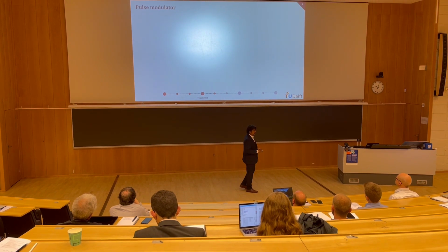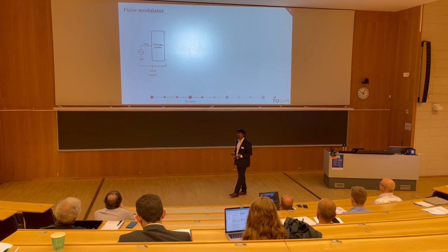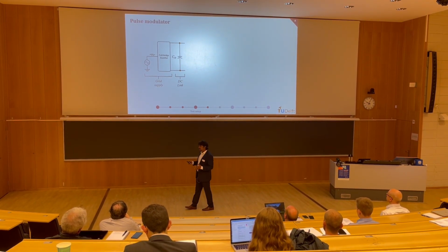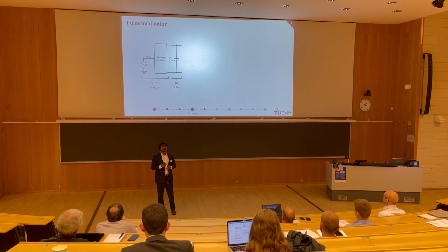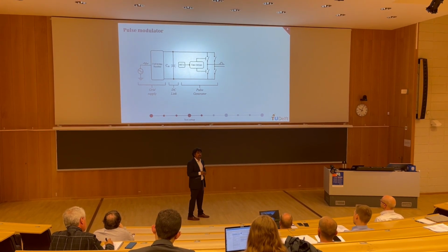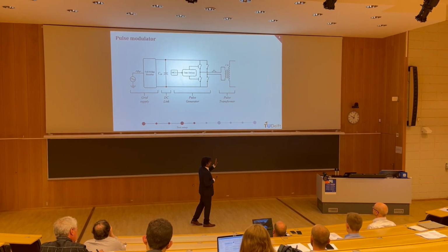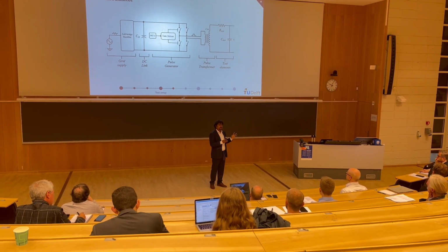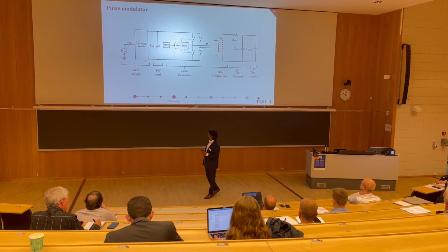The pulse modulator looked something like this. We start with rectifying the grid supply. We then charge the DC link. We had an H-bridge pulse generator to produce pulses. These pulses were stepped up by a pulse transformer of a very high turns ratio. It was 1:50 in our case. These pulses were then conditioned with test elements before finally being applied across the insulation sample.